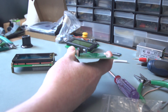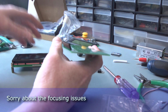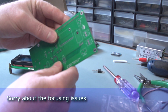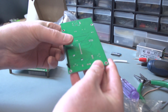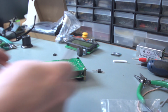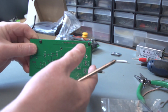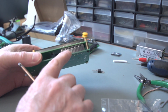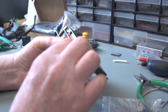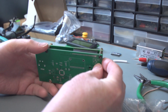Perfect. So the way to solder this in is to actually bolt the whole thing together, and put the actual connector together there. That'll locate this to the exact right angle, and then we can solder the backside, and everything should be correct. Okay, so I've just loosely bolted the whole thing together, and that basically means that the alignment is now correct, and that just pushes nicely into the connector there. That means we can now go ahead and solder this connector onto the board. So let's do that now.